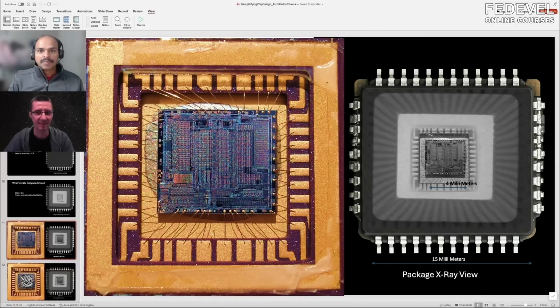This is very interesting, because I always only thought about JTAG as used for board testing, but actually it can be used for silicon testing because, as you said, you have access not to the pins on the package, but to the pins on the silicon, on the die.